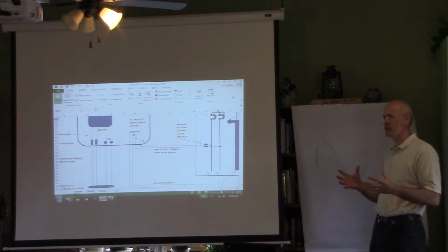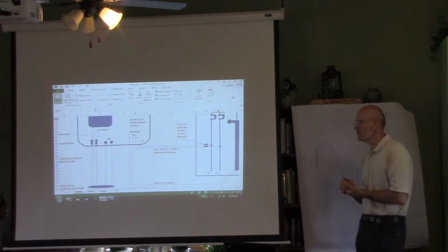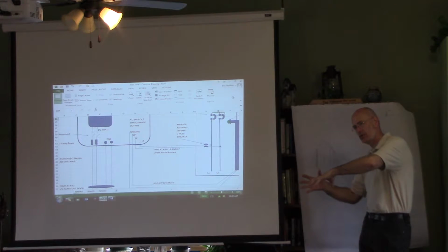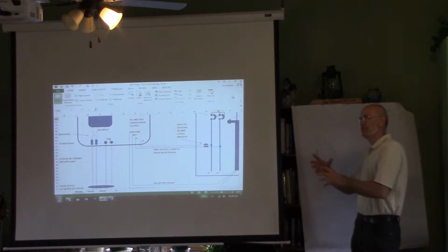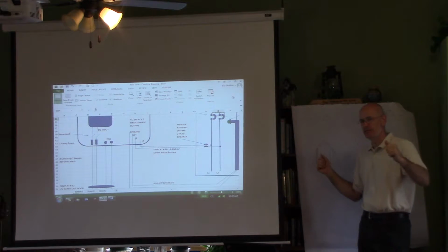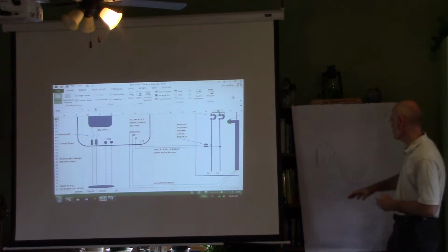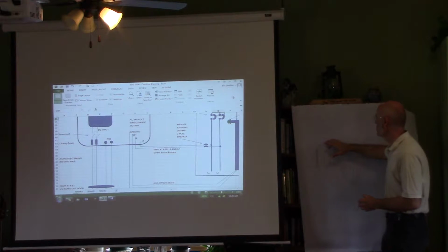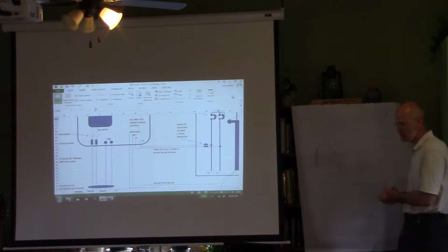If you didn't have the capacitance, it would just blow up. You can't respond that fast. So it acts like a giant barrel of water. You can take it in, hold it for a little bit, and then shut the valve off. I can push it out, make sure it's working, and then start refilling it. So it gives it a reservoir of energy to maneuver these pulses up and down, so that it's taking the power from the solar panels or not taking the power from the solar panels.